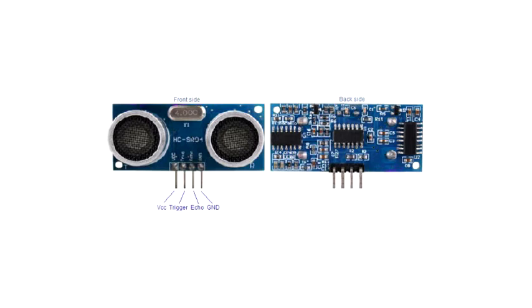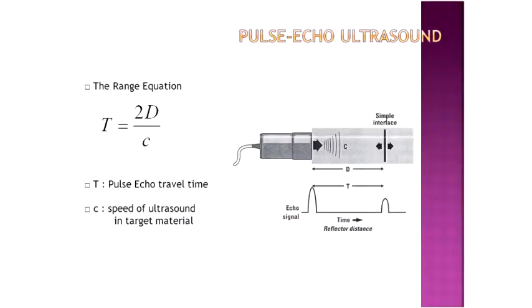The echo pin is considered to be the input to the board. Unfortunately, the sensor doesn't provide distance as an input, but rather the time taken for the sound signal to return. By using the equation 2 times distance equals speed times time, the distance can be determined.